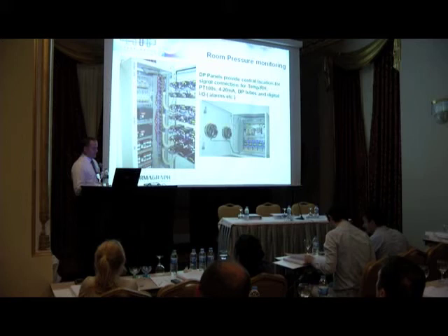You can also monitor your HEPA filters. Again, you would generally do that with magnehelic gauges, but if you do it automatically with this system, A, you don't have to check it daily, and B, when you've got a problem, this system will tell you about it, it will tell you when you had a problem, and someone should take some action.